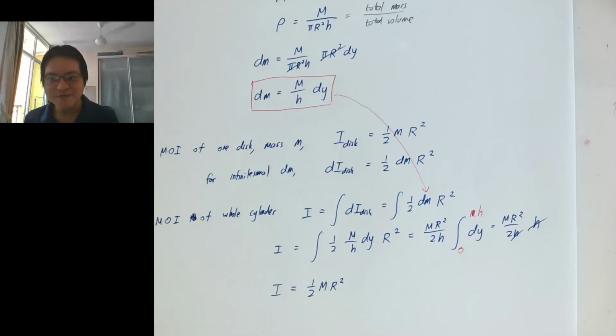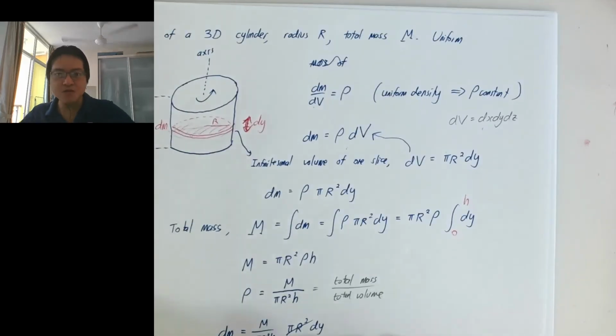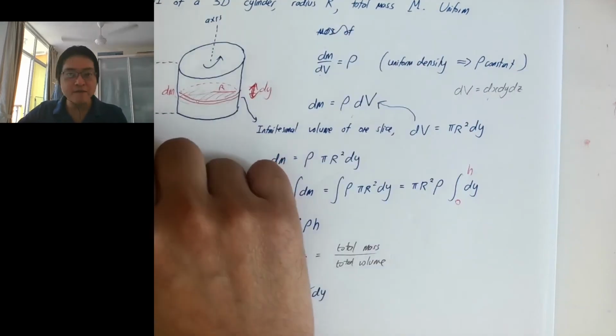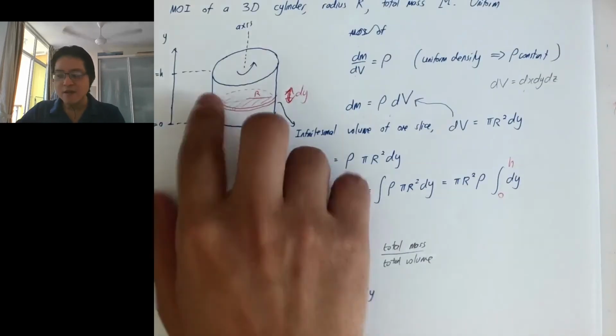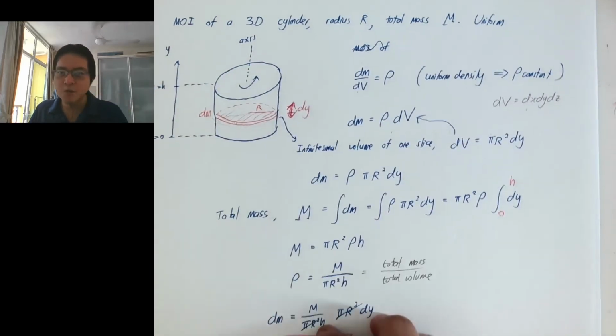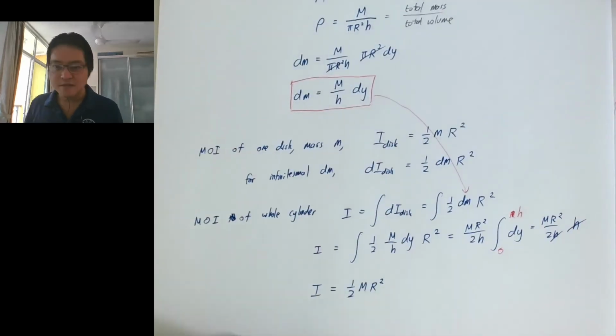Yeah, Wei Zheng. About 80% of the time, the calculation is just about the dimensions of the object. Normally the dy is irrelevant. Yeah, seems like it. If the dimension is parallel to the axis, then the final answer is independent of the height. It only depends on the perpendicular distances. I suppose that should be the main reason why, because our moment of inertia formula mainly depends on perpendicular distances.